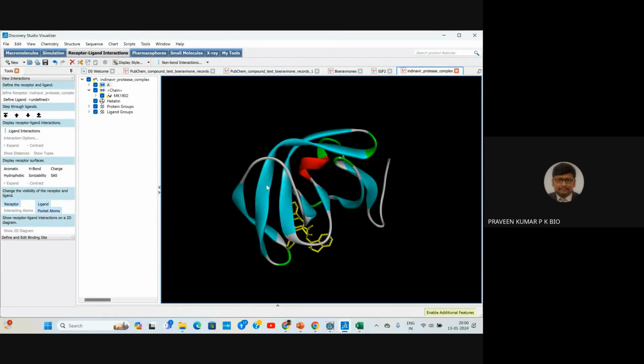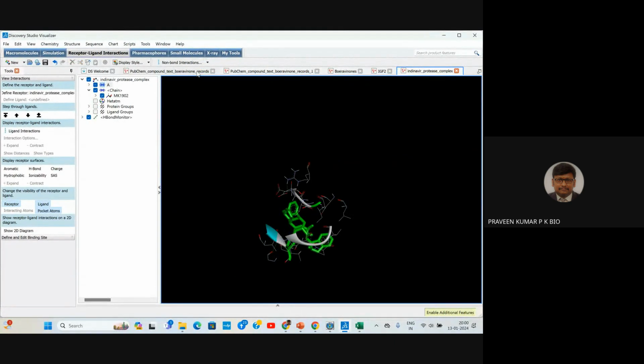If you want to select the 4 angstrom binding site amino acids nearer to the ligand, you use this step. One is Selection, Select Ligands. The next step is Selection, Select Atoms within 4 angstrom. The next step is to click Ligand Interactions, Show Ligand Binding Site Atoms.